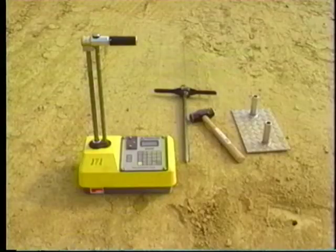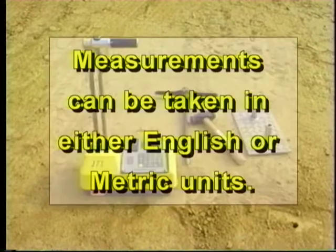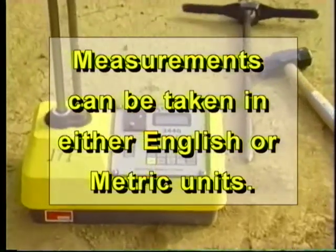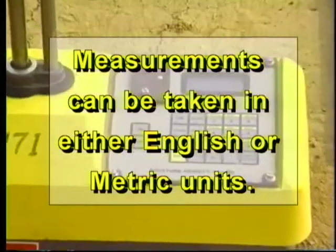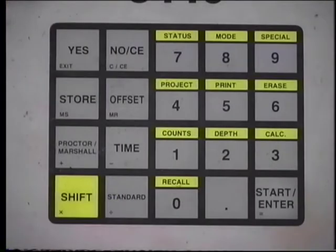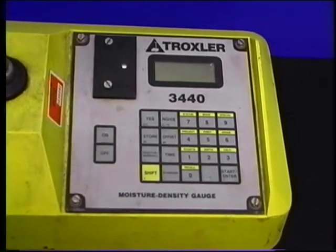Prior to taking measurements, you should determine the unit of measurement you want for screen displays or printouts. The device allows you to choose between metric or English units, kilograms per cubic meter, or pounds per cubic foot. To execute the Set Units function, press Shift and Special. Follow the display instructions to get the required units. The device will remain in that mode until it is reset.